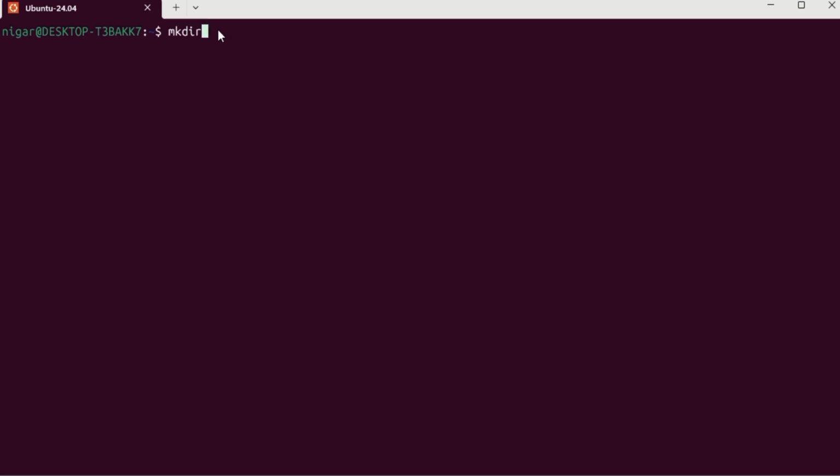So for that, what's next is mkdir -p, right? And then this is the name which mostly all the developers use, ros2_workspace, and we create this src folder. This src folder is actually very important. We put all our packages and simulation files in this. So whenever we do coding in ROS, we will be dealing with this folder most of the time. So with this command, we have already created our workspace.